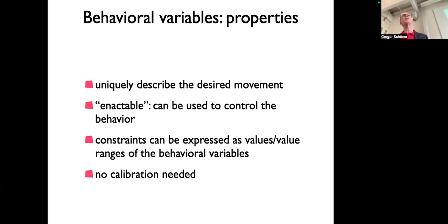That means you can make sure that any desired rotation rate for the vehicle's wheels can be realized by the wheels. Now, there are limitations, of course, if the vehicle has mass and inertia. It depends on how strong the motor is, whether that control is sufficient. If you make a weak motor on a heavy vehicle, it might not be able to do that. That's by design. You're not designing the vehicle this way; you're not giving it too much payload. So you can eliminate that problem. The other control problem is, of course, that the contact between the wheel and the ground is not guaranteed to be that way.